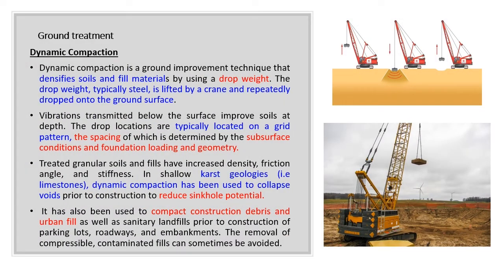Dynamic compaction and consolidation using a tamping system can enhance the ground condition up to a considerable depth. The ground is consolidated by repeatedly dropping specially designed tampers into the ground. Ground conditions suitable for dynamic compaction include natural ground soils, made-up ground, and landfill refuse sites. The technique can also be used as part of more significant earthwork operations where the ground is built up in